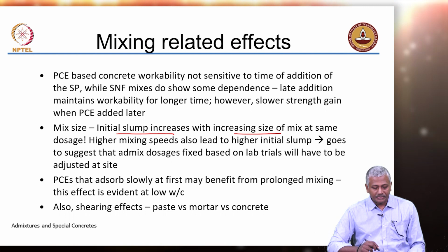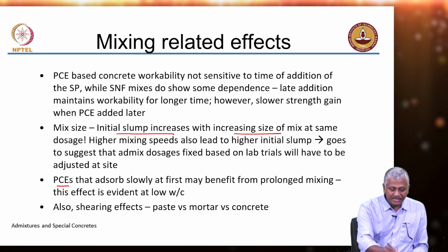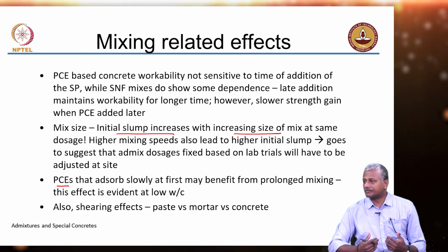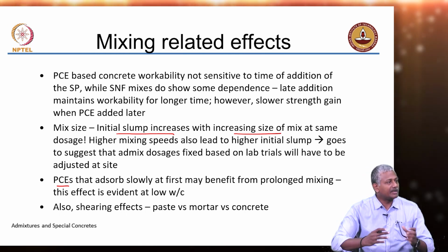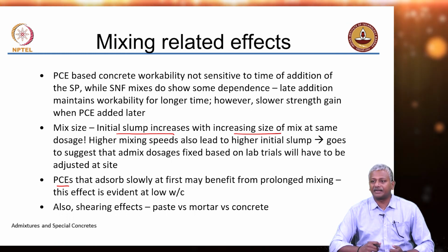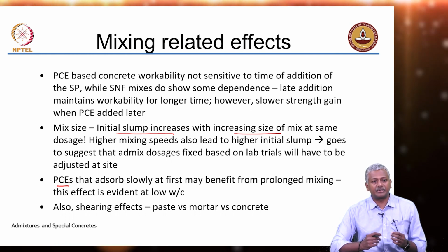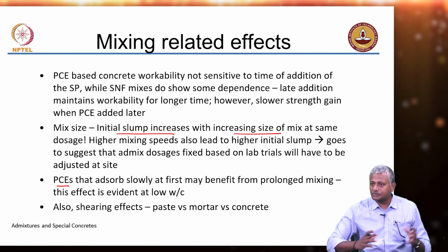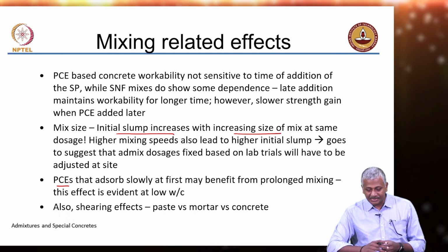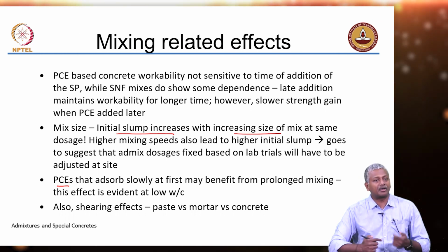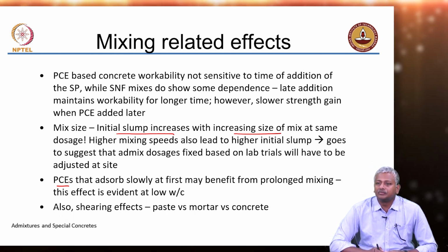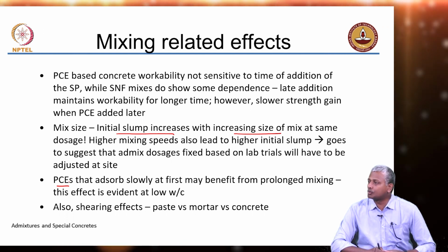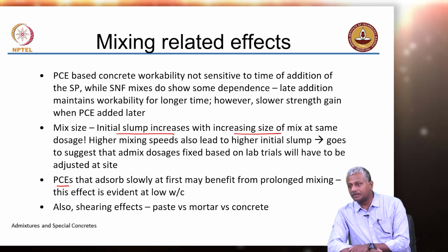Okay. So, one more aspect is PCEs that adsorb slowly at first. See, SNFs are charged, so the adsorption is almost immediate, but PCEs are not like that. They have long side chains, they are bulky, they do not move around that fast, and they adsorb slowly onto the cement. Now, in such cases, if you mix for a prolonged period of time, you may benefit better from the use of PCE. This is especially true when we talk about ultra high strength concrete, right.